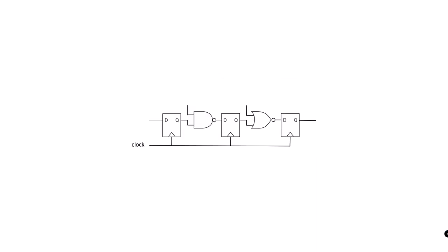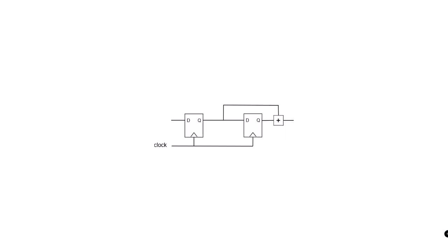The sequential machine imposes order on digital signals using registers. The register state changes at certain times governed by a clock signal. An event on the clock signal causes the registers to read their inputs and update their internal state. Changes on the combinational outputs will affect that state only at certain times. The result is a sequence of state values held in the registers. We can use a sequential machine to compute an output from previous states as well as the current inputs, something that combinational logic can't do.